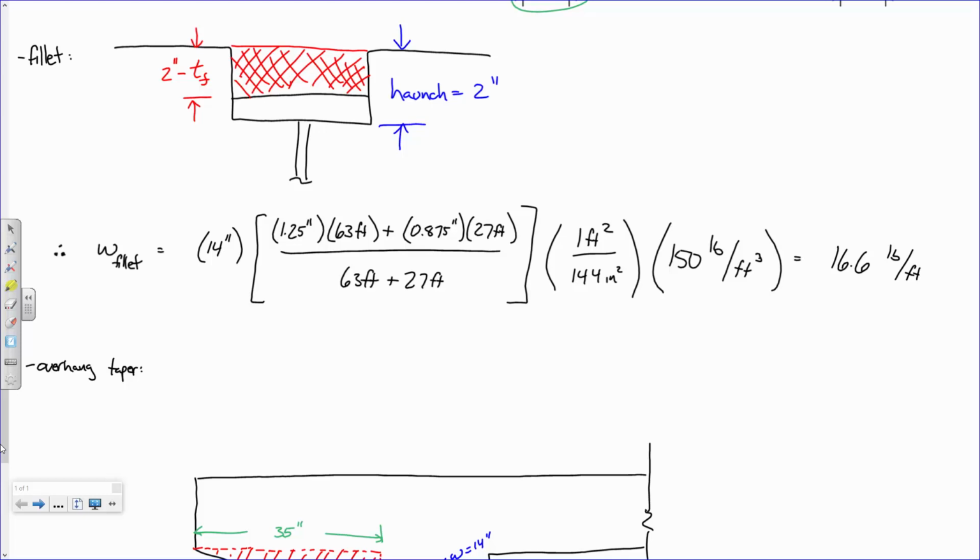Let me put it like this. If you got a beam that's like 200 span, 300 span, some massive structure, the top flange in some regions might be 2.5 inches thick. So obviously a 2-inch thick haunch wouldn't make sense in that.